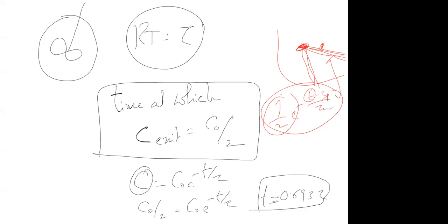Bypass happens because of, let's say, so many years of operation. There will be some chances of bypass. Bypass doesn't mean that you need to create it externally. Sometimes you may need to create it externally because of some reason, but sometimes it may happen inside also. Bypass means something which is going without touching the reactor. The name itself indicates that.